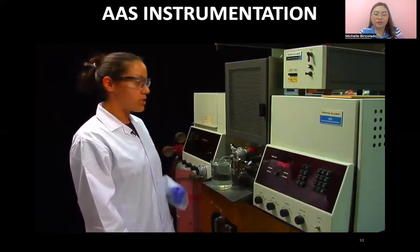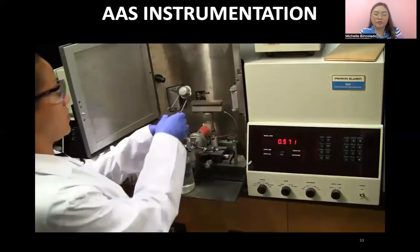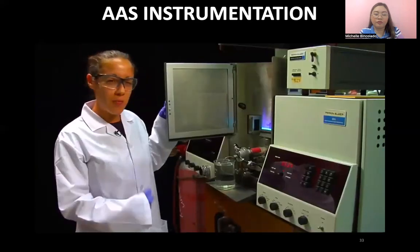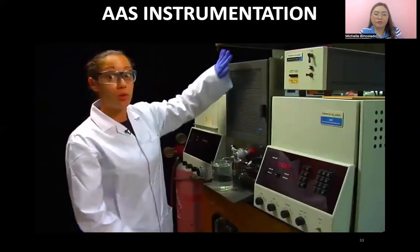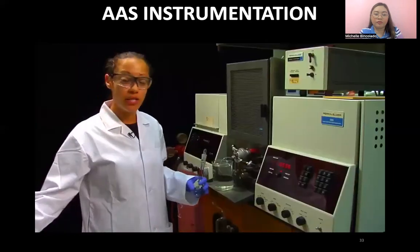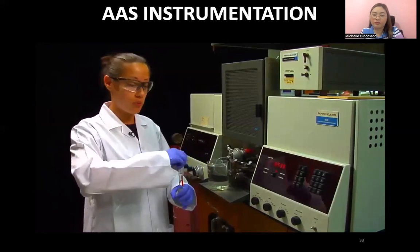So just to start up the instrument, give me some oxidized air. Just use a regular sparker. And that's what your flame looks like. You get used to the pump in the background. It's quite warm, so you want to keep the door closed once you have it ignited. You already have all your standards prepared. You want to start off with your 0 because you want to zero the machine.